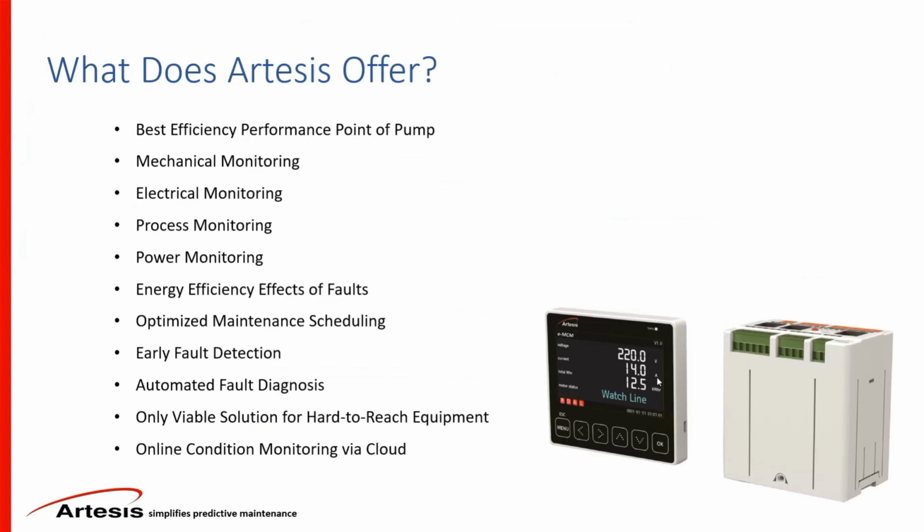and you will have more of a preventative approach. So for instance, if the pump performance curve shows you that the pump is running at a cavitation point, and maybe it hasn't damaged the impeller yet, you will see that. If you prevent that, it won't turn into damage pits on the impeller. This will be before we see anything on the spectrum that it has actually turned into a cavitation problem.